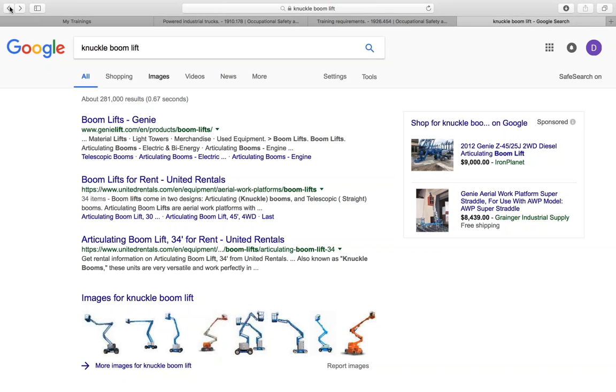Also, some models include an operator station at the ground. They also call it the dead man controls in our industry. What does it mean? It means that the lift is supposed to be able to be controlled from the bottom as well, just in case an employee loses consciousness, is incapacitated, or dies up there. Look on page 28, folks, and you'll see the controls there. If you look at the JLG boom lift, right above the rear right tire, on the left-hand side of where it says JLG, those are actually the controls. It's just a little hard to see, but those are actually the controls.